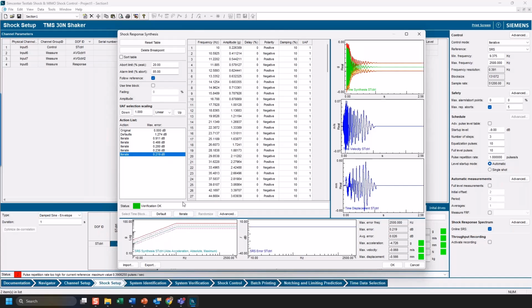But you reach a certain point where you start to get divergence. Nice thing here is I can go back. So let's see, this has a time domain acceleration max of -4 Gs, max displacement of 0.56 millimeters. If I go back to my other function here that has less error, it's about the same. So I'll just pick this to work with. There's some other things to fiddle with as well.